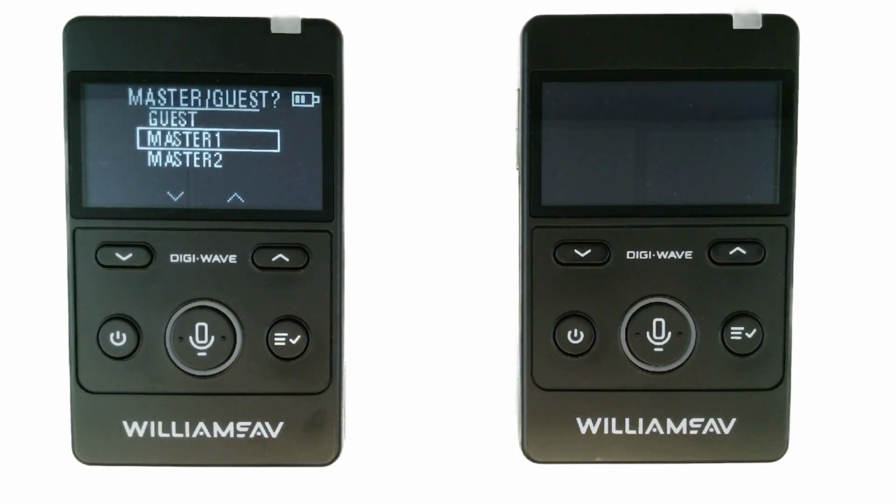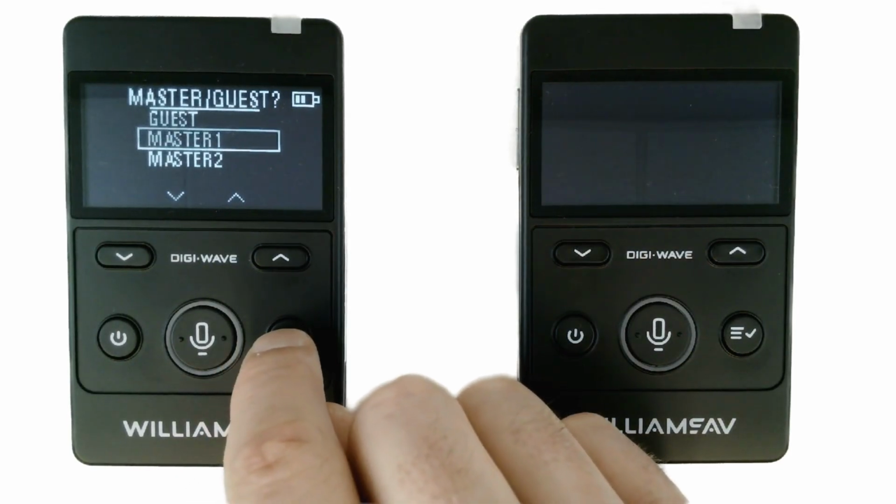In every Digi-Wave configuration mode, at least 1 Master or Master 1 DLT is required. Each group must have 1 and only 1 Master 1 device. All other DLTs and DLRs will sync to the Master in the group. It's also important to remember that the Master DLT determines the communication range for the entire group. Select Master 1 so that we can establish a group that all other devices can sync to.